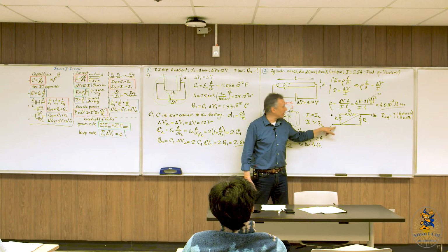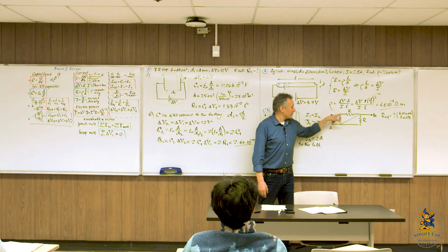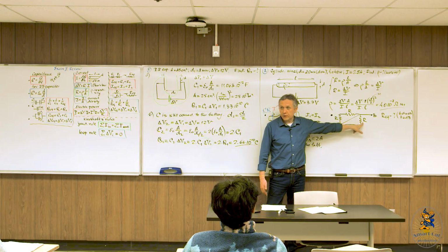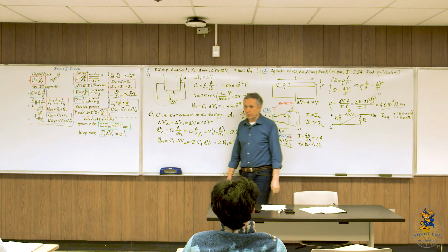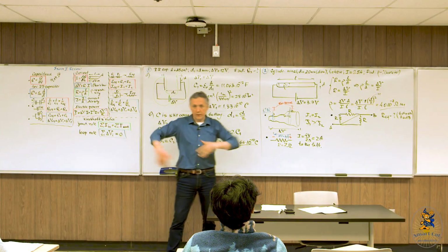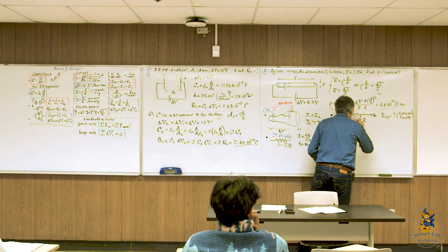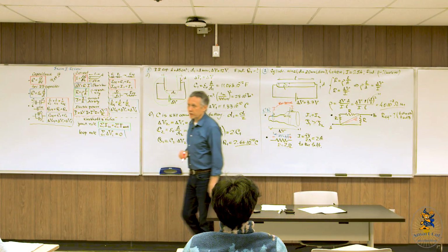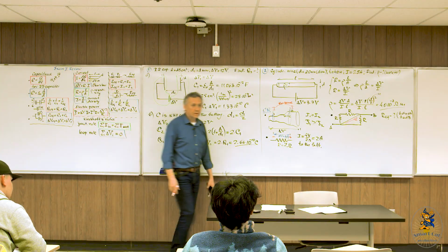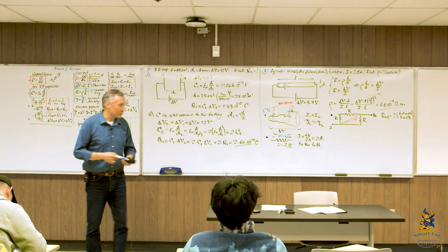Here, the same situation. When electrons come to this point, they have three options: either hurting themselves really deeply going through these two resistors, or hurting themselves getting through that resistor, or just going through the open door. Of course, they will go through the open door, which in this case is an extreme, with basically no resistance. All current will go this way, bypassing those three resistors completely. So those three resistors will do nothing here. Of course, it's an absolutely stupid circuit. No one would assemble anything like this.